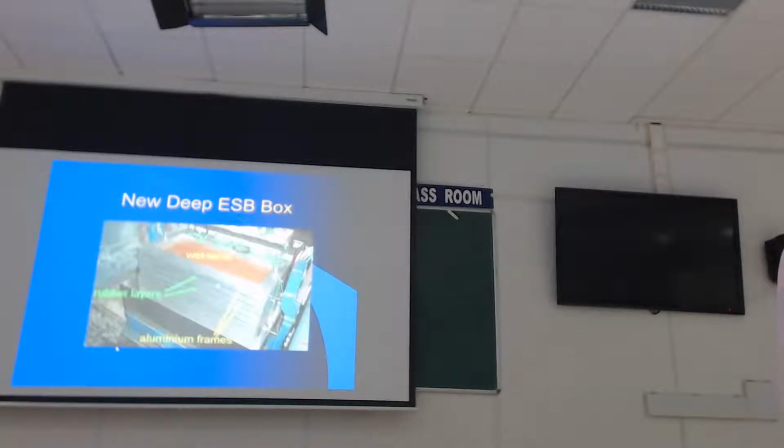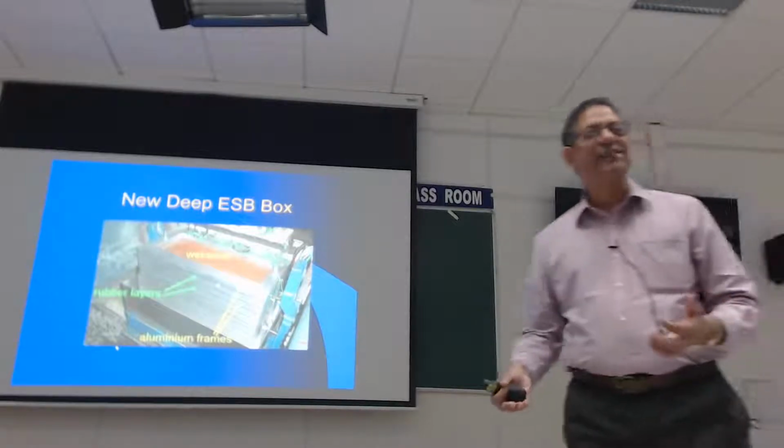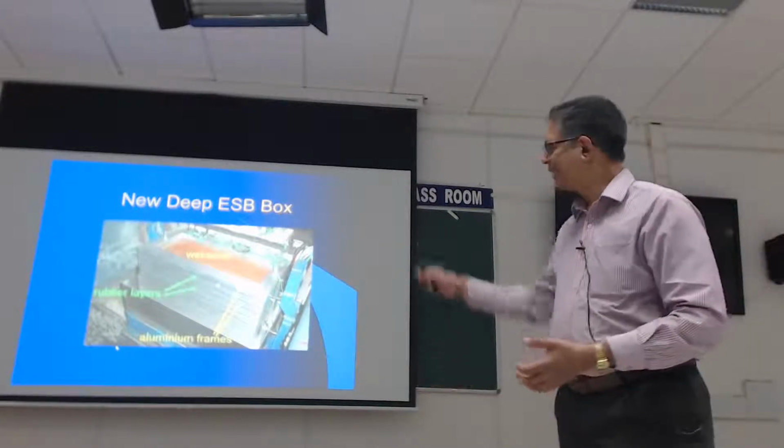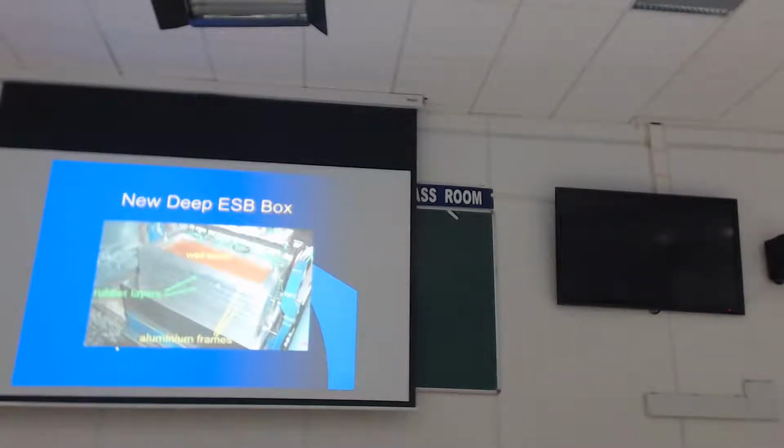Okay? The reason is soil is bloody heavy stuff. So even the largest shaking table in the world cannot handle more than 6 meters of soil, whereas a tiny little box like this can simulate 40 meters of liquefiable soil depth, which is more than what you need. And that's a big thing to remember.